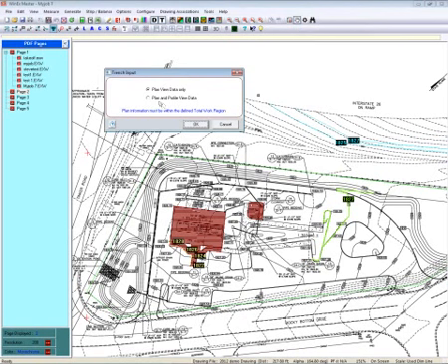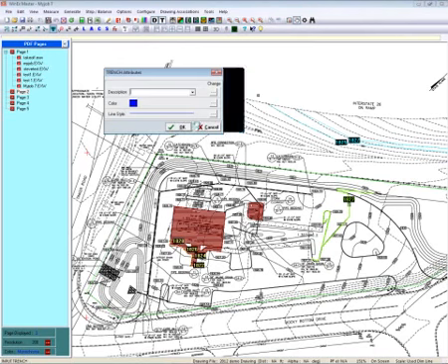In our software, you can work from plan and profile view at the same time. So if you get plans like that, like I know most of you do, just know that you can begin your takeoff on your profile view and then directly import it onto your plan view, or vice versa, however you want to work that routine. I've just got a plan view here, so I'm going to use that. I'll say OK. Name your trench and choose your color.